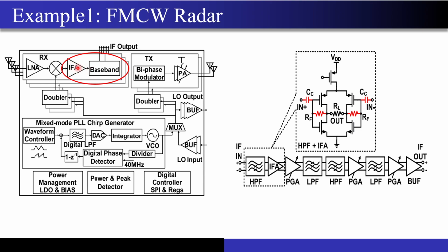So this thing is not that easy. You may think that this is just a one-amplifier structure, but if you look, this is a complete chain of filters as well as amplifiers, and not only amplifiers but programmable gain amplifiers. Now if you have a little bit of knowledge about analog circuits, you can easily identify this structure. Can anyone please tell me what these two transistors constitute? What do they call it? One PMOS is there on the top, one NMOS is there on the bottom.